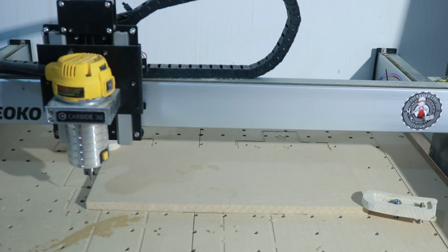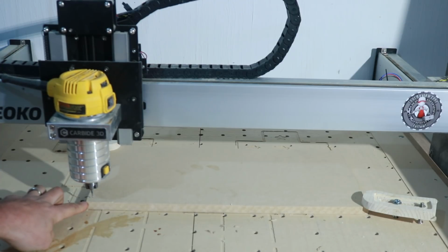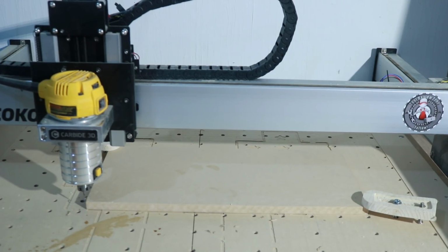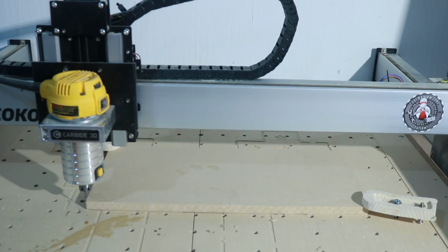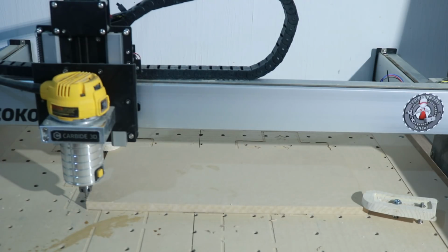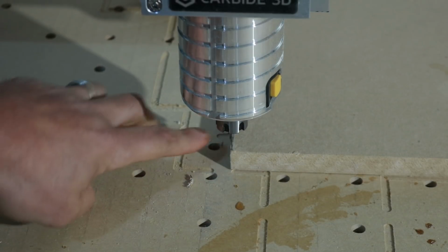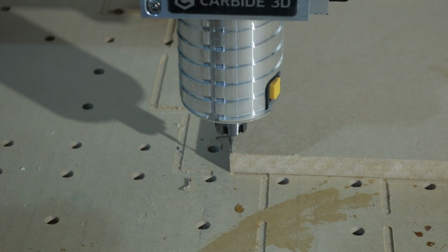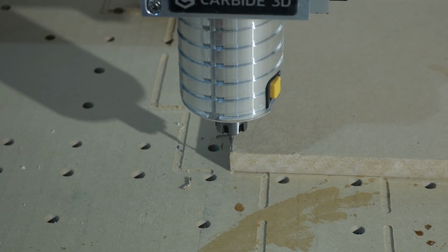We'll bring that down, and we want to go right there in that corner, just like we showed you when we were setting up the design. It's not going to be perfect right off the bat, so you can change it from millimeter. There you go. Come down a little bit more. I'm going to get a piece of tape here, and I'm going to make sure it's zeroed out. So now we have this basically right where we want it. Now that we have that zeroed out on that bottom left corner like we put in the design in Carbide Create, we're going to come over and we're going to zero out this machine.